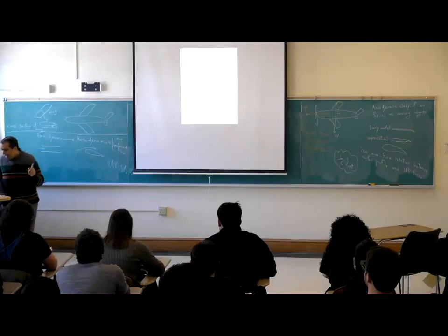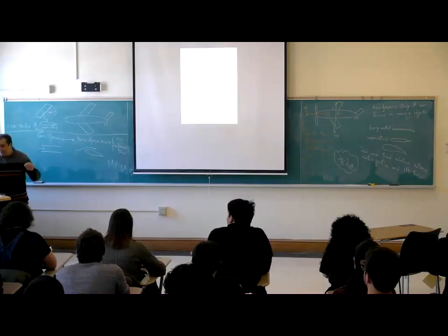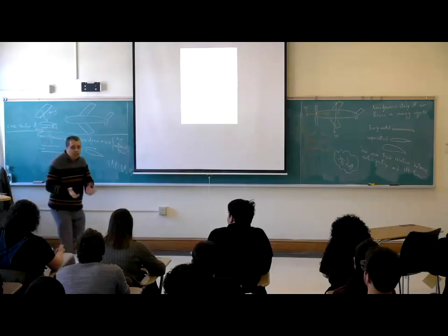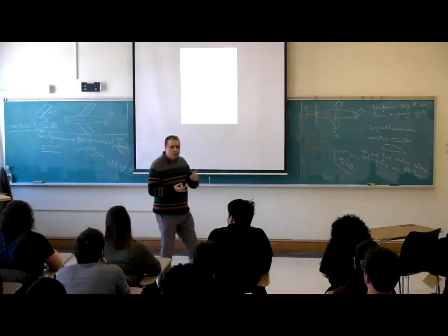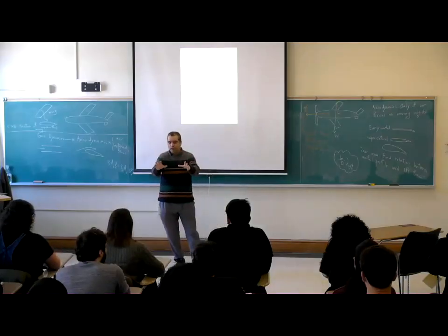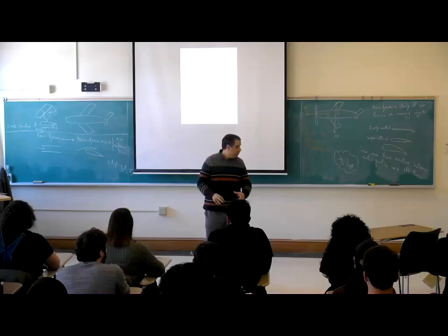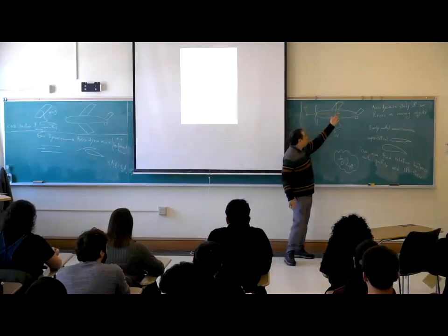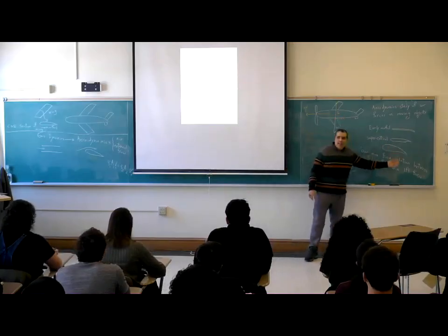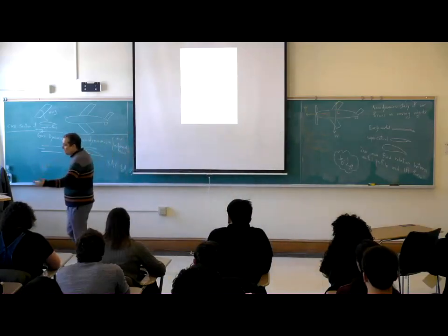Okay, so we have conservation equations, fundamental fluid dynamic principles, elementary solutions of incompressible flow. We go to the potential flow equations: source, sink, doublet, vortex. And I should tell you one thing: every component of the lift force comes from vortex. Everything comes from vortex. This shape creates a vortex for the airplane, and vortex creates lift.